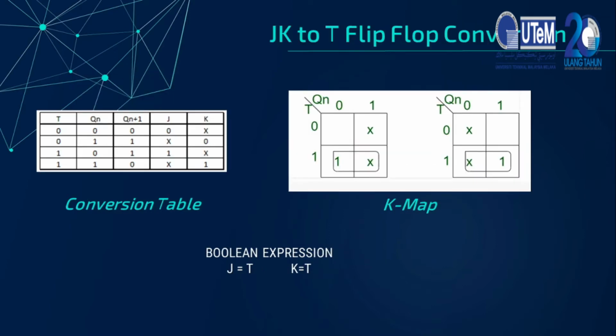Let me explain briefly the toggle flip-flop. The toggle flip-flop changes state when the clock input applies T equals 1 and remains unchanged when T equals 0. The transition from 0 to 1 will cause the output to toggle, giving the flip-flop its name. The T-type flip-flop is basically a building block of many digital circuits, including frequency dividers and digital counters.